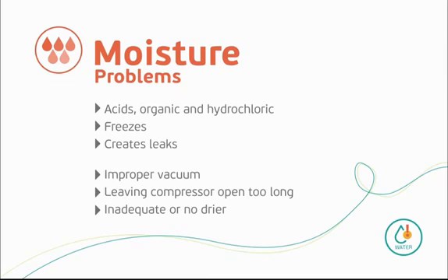Moisture can freeze in the system's metering device, shutting down the system, as well as in braze joints, where expansion can crack the joint. The moisture can come from improper evacuation during the vacuum process, or not purging air out of service hoses. Tube plugs should only be pulled right before hooking up tubing for brazing. Any residual moisture needs to be trapped by a properly sized dryer.